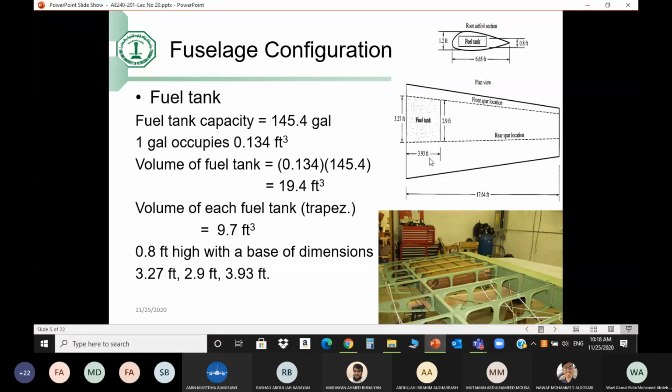If the fuel tank is very long, let's say the fuel tank will go to here, that would not be acceptable, because that will mean the wing is going to be very heavy. It might break. It's not designed to carry that much fuel. Typically, fuel is inside the inner 1/3 of the wing. So if that's the case, then we might think of having a 3rd fuel tank, maybe in the fuselage, depending on the type of the aircraft.